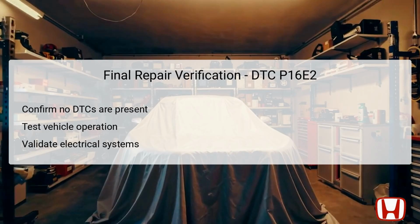After conducting all necessary repairs or inspections related to DTC P16E2, it's essential to perform a final verification to ensure that the issue has been resolved. Begin by clearing any stored diagnostic trouble codes from the PCM, and then perform a thorough test drive to observe the vehicle's performance under various conditions.